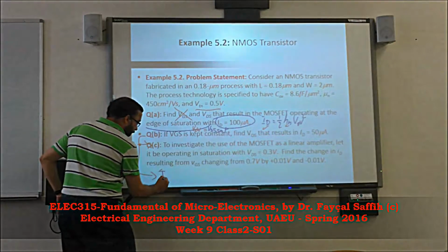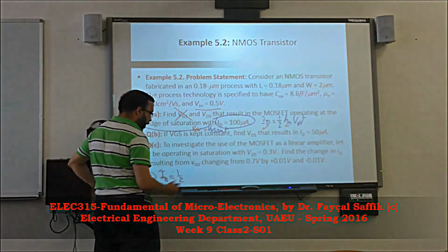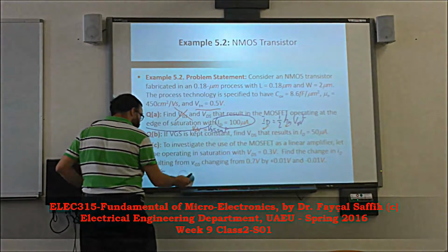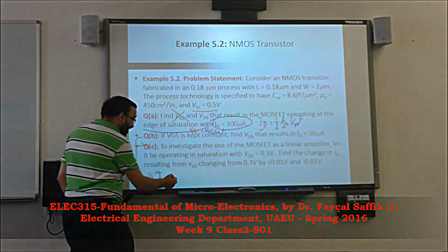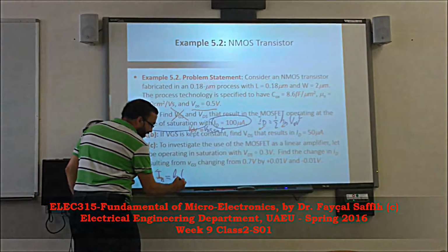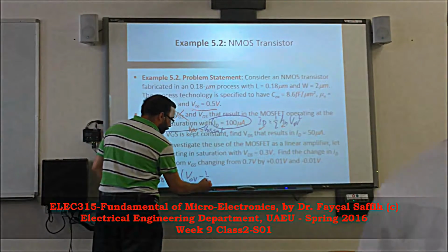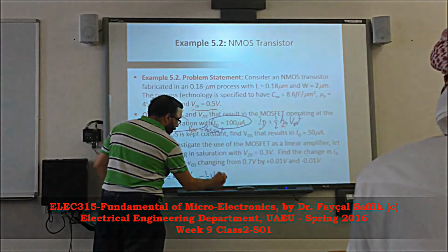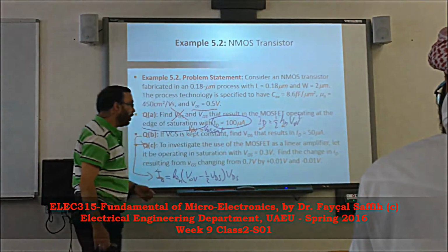Okay. ID is equal to half Kn times (V_ov minus half VDS) times VDS. And just solve for VDS.